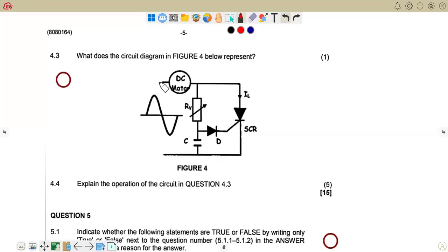During the positive half cycle of the input signal, the SCR will turn on and the anode to cathode voltage will drop to the conduction value, resulting in reduced gate current. During the negative half cycle of the input signal, the SCR will be off.